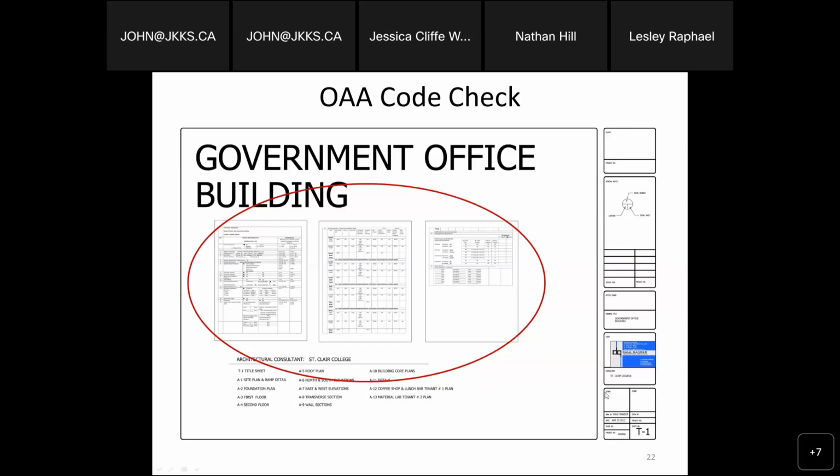Typically that's where the architect or engineer would officially stamp the drawings. So the information would be deemed as completed, ready to go out for tender or bid, or for actual construction or for building permit, once those drawings are stamped and approved by the architect, engineer, or in some cases, if it was a smaller project, the BCIN designer.